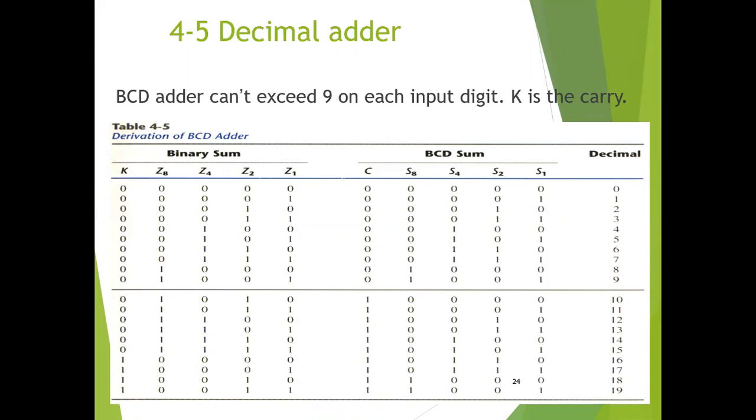The operation requires input bits together with an input carry from a previous stage. If two decimal digits in BCD are added, then an input carry is also required from the previous stage. Since each input digit does not exceed the value of 9, the output sum will also not be greater than the maximum possible.